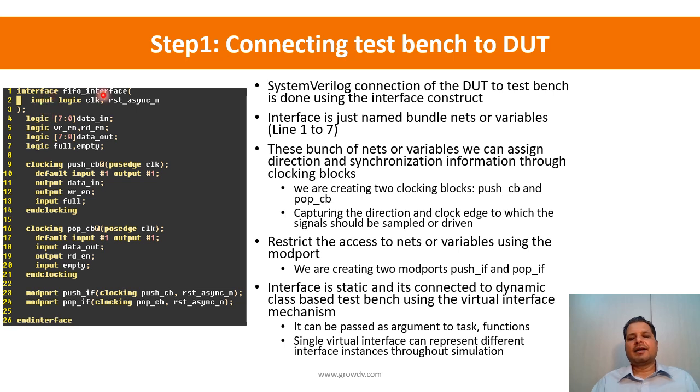An interface is just a container of wires, and when I look at the interface, I can access any wire in any direction. For example, data in is of the type logic, so I could either be driving it or reading it, right? So there is no sense of direction, and the sense of direction is provided through these Modports. Modports are views to these wires; whether we look at a particular wire as an input, output, or in-out is decided by your Modport.